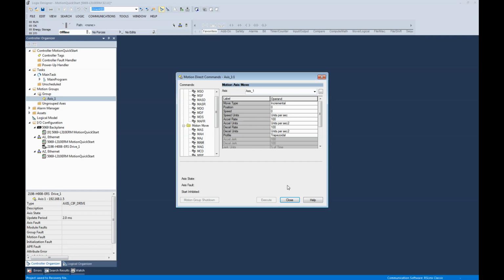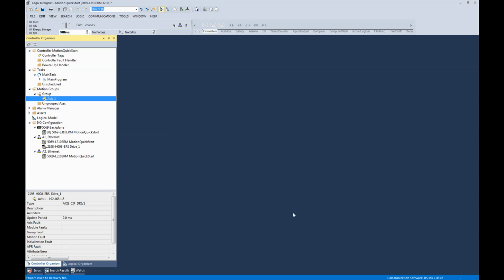And note, if you are doing troubleshooting with this, it is much better to have the hardware in front of you so you can check the encoder part number. You can see if there are any digital inputs, for example. You can see on the 5500 how your DC bus and AC bus are configured, because there's any number of ways, given that it's a hybrid solution. So make sure you have the hardware in front of you when you're doing this.